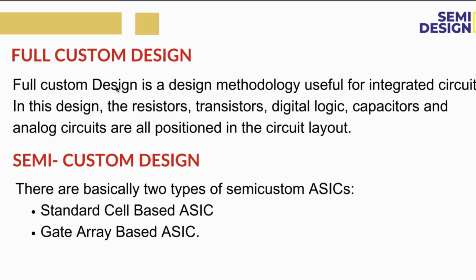So next one is the semi-custom design. Semi-custom design is also one of the alternatives to the full custom design. Here we can use the components from the standard library. As the name semi-custom suggests, we take the components from the library and customize them. The components are pre-designed, so some mask layers will be there, and we customize the pre-designed logic cells according to the design.